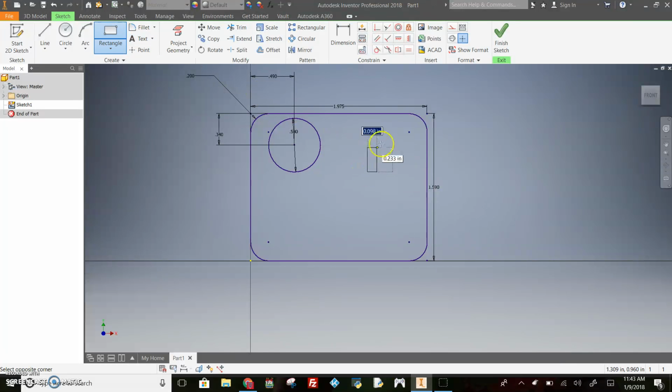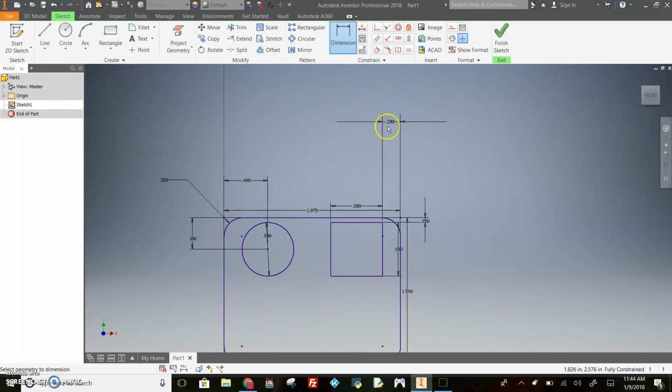This rectangle has a dimension of 0.58 for both sides. And we'll dimension it from the top to the top of the rectangle, which is going to be very small. It's only going to be 0.05 inches. And then the sides, from this side to this side, is going to be a little bit bigger. It's going to be 0.2. There we go. Our rectangle is now done as well. 0.2 inches. I'm going to drag that down. You can see it. There we go.